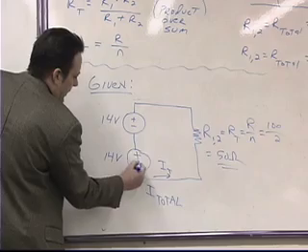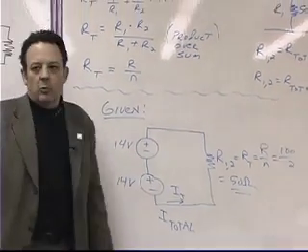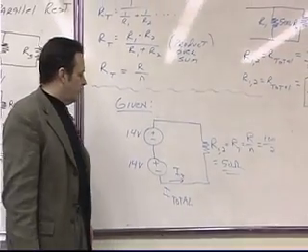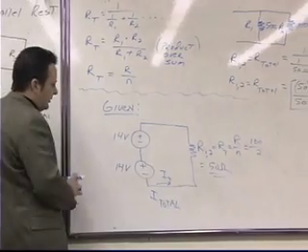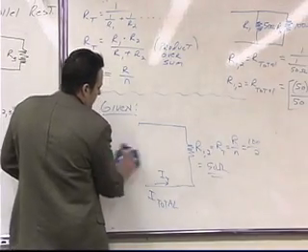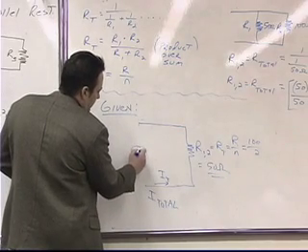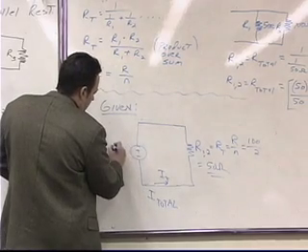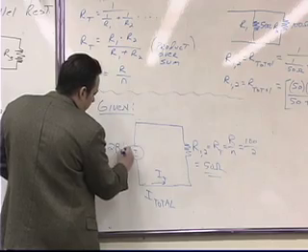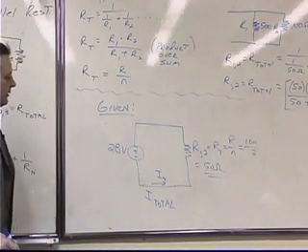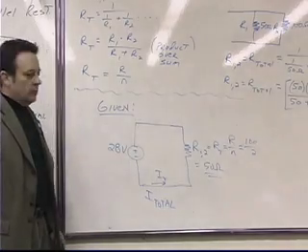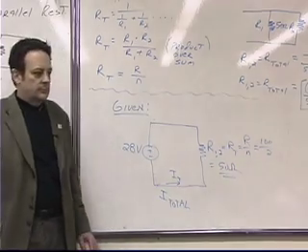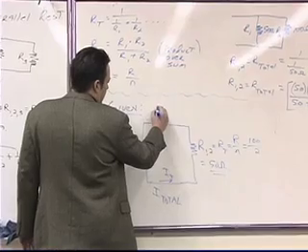So generally you're going to have the batteries polarity so that they're working to aid each other. It's called polarity aiding instead of polarity opposing. So I could simply take these two batteries and substitute one single battery, and this would be 28, right? 28 volts. And then if I wanted to find the current, what law am I going to use now? Ohm's law. Right.